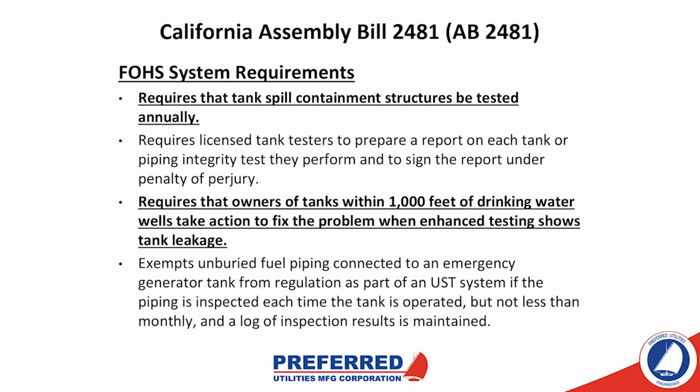A few more points on fuel oil handling system requirements of AB 2481. Again, the important ones to us are in bold. The first one, AB 2481, requires that tank spill containment structures be tested annually. That's commonly known as an annual CERT. It needs to be done by a certified technician, and by certification, that is state certified, not factory authorized, that kind of thing.